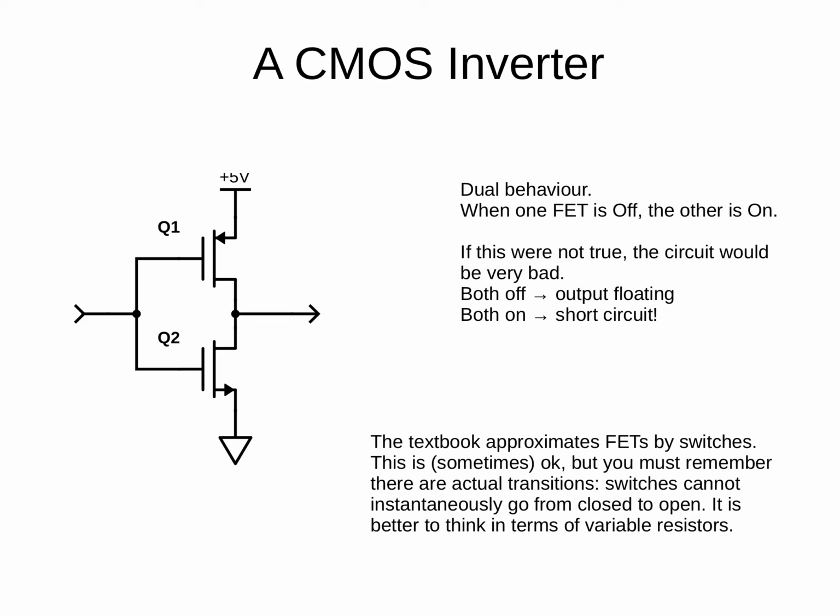We will see all our logic gates have got some sort of a symmetry. You can split them along the middle. The output's going to be this middle point here. We're only going to have p-channel FETs above the middle line, and we're only going to have n-channel FETs below the line. We can think of FETs as either being on or off. If a FET is on, then its channel resistance is small. If a FET is off, then its channel resistance is large.